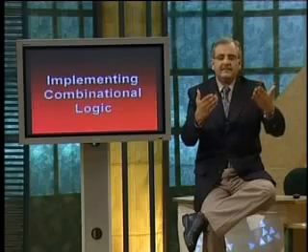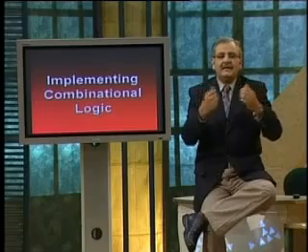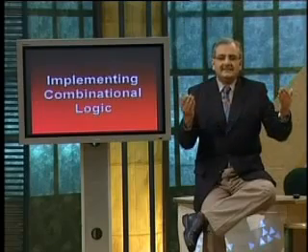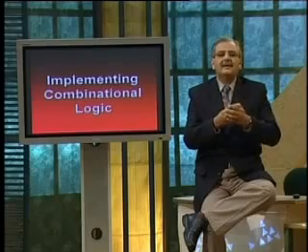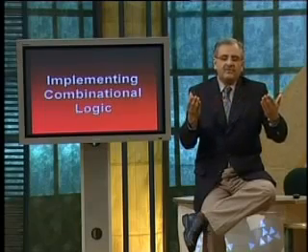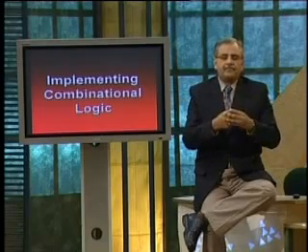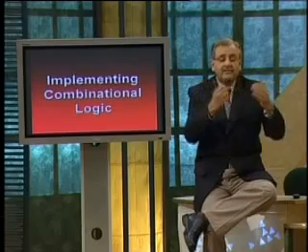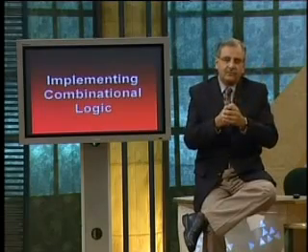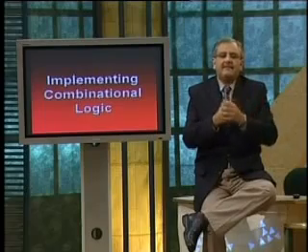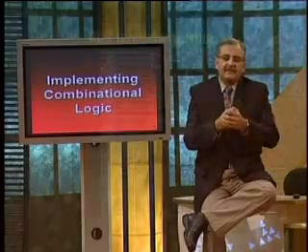Basically, if you look, you can see 8 max terms in the function table. So you would have 8 OR gates. Now the output of all those 8 OR gates would be connected to an AND gate, of course, which is doing what? It is doing the sum of products, or rather product of sums. The AND gate has 8 inputs, of course. So let us have a look at the 3 different circuits. We will summarize this again later.